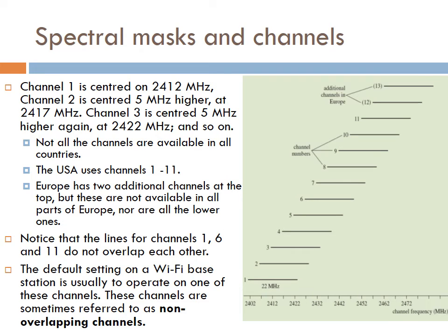As we have said, we don't have only one channel in the case of this standard. That's why we are representing the channel frequency by 0 in the spectral mask. However, in these standards we have more and more channels. So the first channel has its center frequency at 2412 megahertz, and the rest of the channels are spaced by 5 megahertz higher.